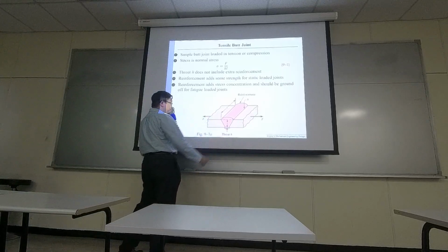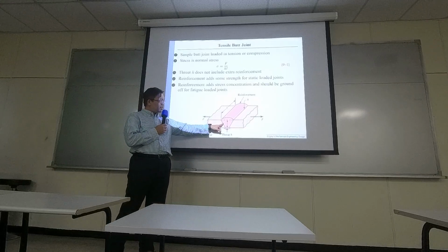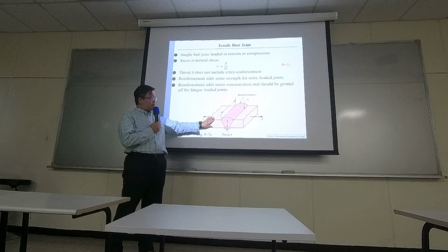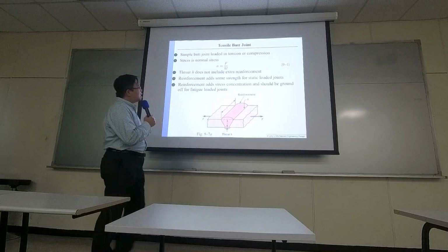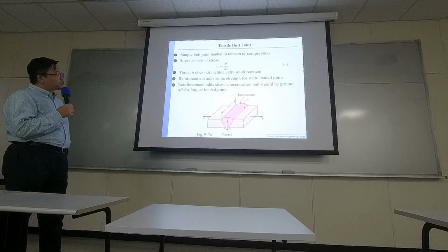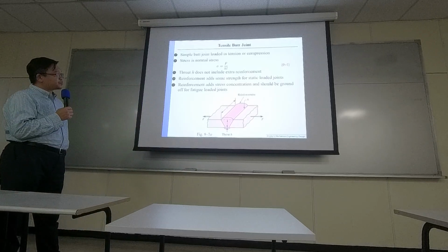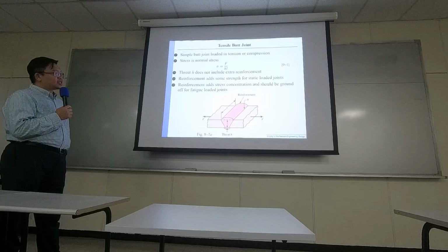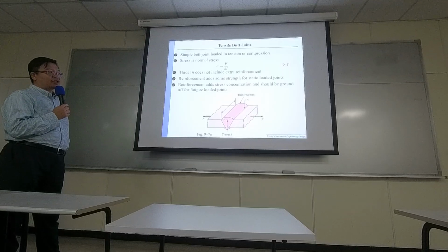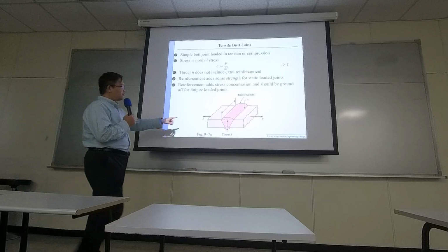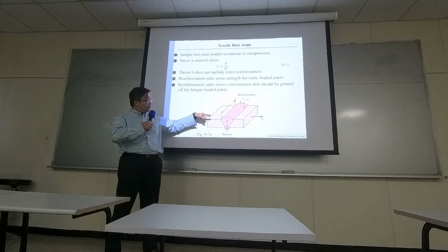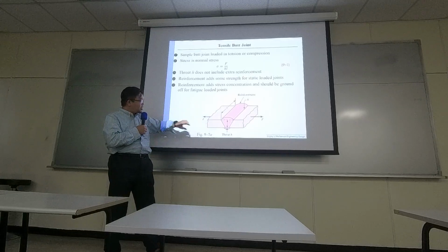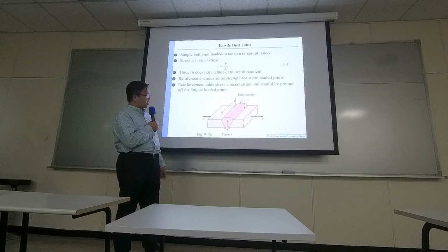It looks like a triangle because some area of the original plate was melted, and at the end you end up with this geometry. And we usually assume, you have to figure out what's the effective stress area. For this particular case, if you are pulling the plates from both sides, then the effective stress area would be the cross section, the rectangular cross section.